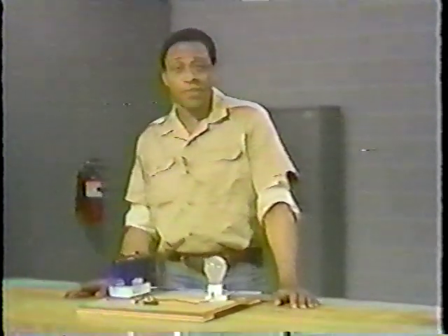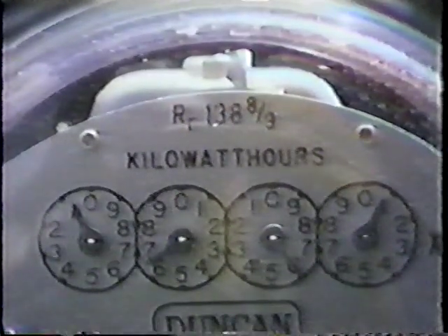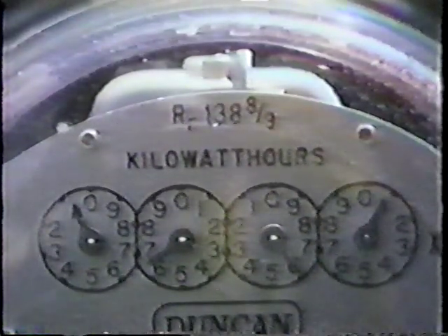Now, what's a watt hour? Well, it's a measure of electrical energy. To get watt hours, you multiply power by time. A watt hour is the amount of energy used when 1 watt of power is delivered to a device for 1 hour. But a watt hour isn't a heck of a lot of energy. You'll be dealing in terms of kilowatt hours most of the time. A kilowatt hour, or kWh, is equal to 1,000 watt hours. Electric utilities use kilowatt hours to determine how much energy the customer uses, and they bill accordingly. What you pay is based on what you use.